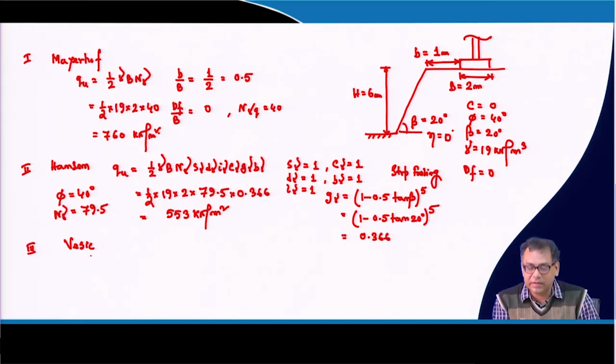Remember that if it is eccentric loading, again you have to apply, as per Hansen, whether it is parallel to L or B; all these issues that I have discussed you have to apply here. Here I have taken the simplest one, the strip footing, vertical load, no horizontal load, just to show you how we can incorporate the sloping ground effect.